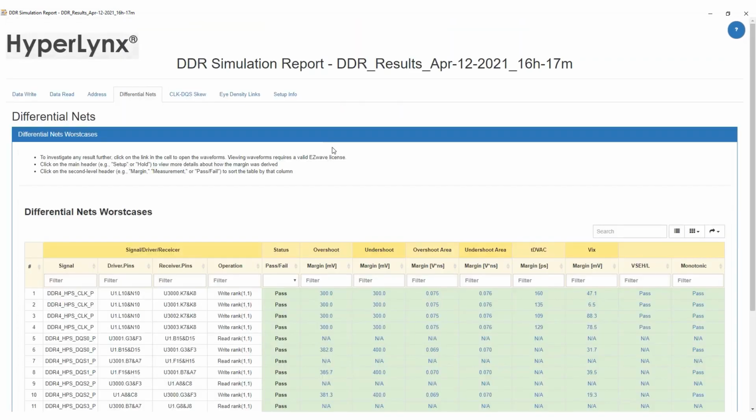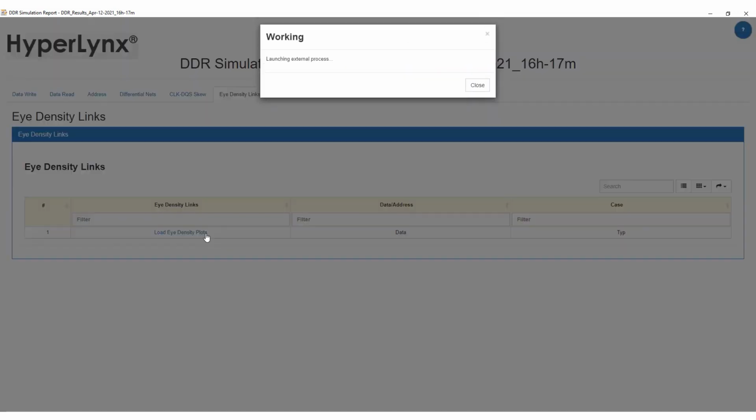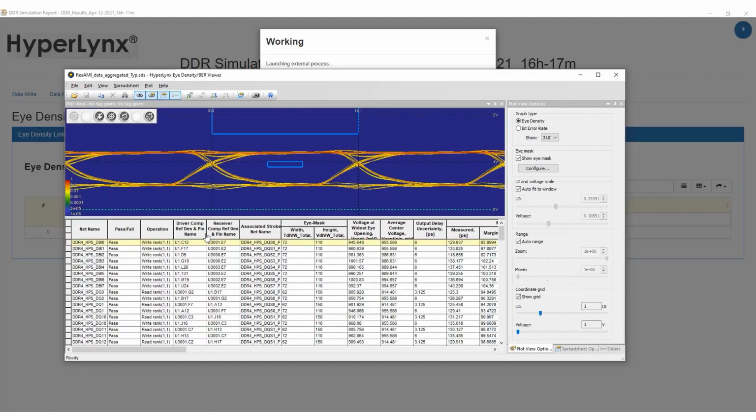This is very important for me as a PCB designer, because this reflects if the PCB layout is robust and passes the final sign-off when other effects like crosstalk and power-aware simulation are considered as well. We can see that we are in very good shape with regard to the DDR4 interface. In the next step, we want to make sure that all other nets are electrically correct as well. This is done with HyperLynx DRC.